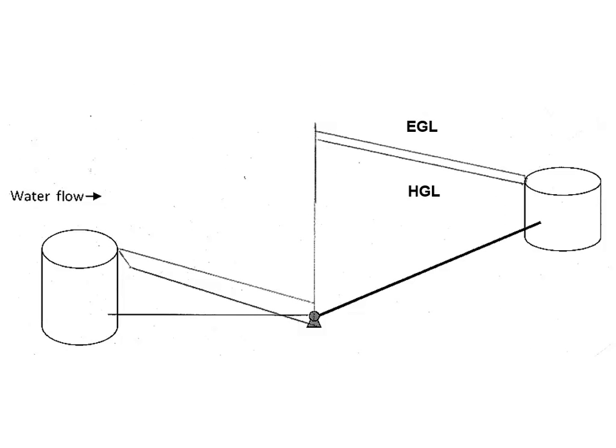So what are the characteristics that ought to be there? Well, first thing that jumps out at you is that since it's a pump, there should be this sudden jump up. It's not a gradual thing. It's just instantly on the left side of the pump, there was low pressure, and on the right side of the pump, there's high pressure. So there's this vertical line where both the EGL and the HGL jump upwards.